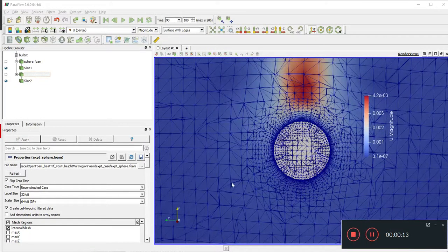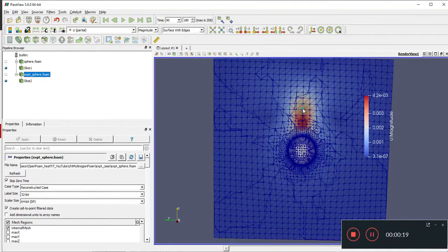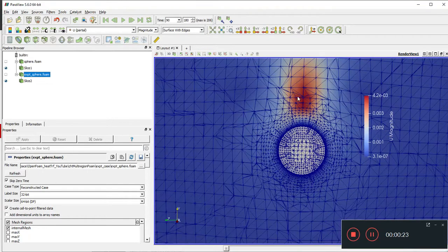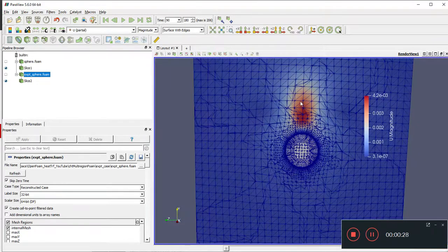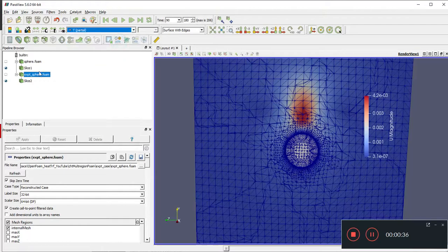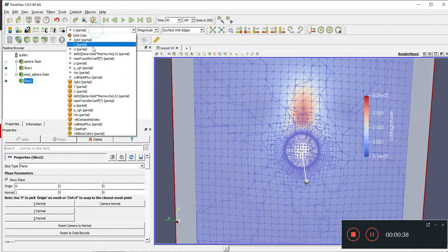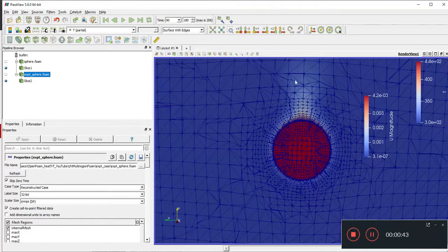So in the last video, we were talking about the plume here getting mixed up because there is this mixing effect over here. The plume gets mixed because of the big mesh size. So what we want to do is probably to change the mesh size. You can see there is a plume here.